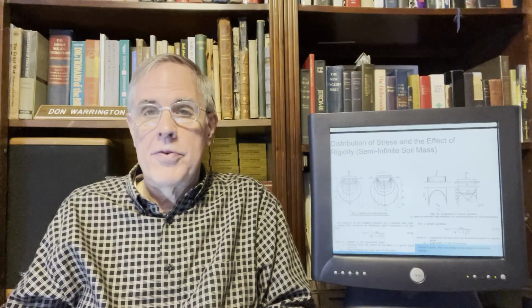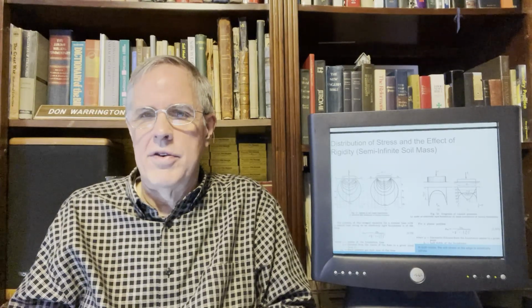You recall with beam theory you have a stress distribution from the compressive side to the tension side of the beam, and how much it depends on the old Mc over I formula for your maximum. Well, the only difference between beams and plates, and I say only, it's kind of a big one, is that plates do that in 2 dimensions. And in some cases they're curved, although most of what we deal with in geotech are flat.